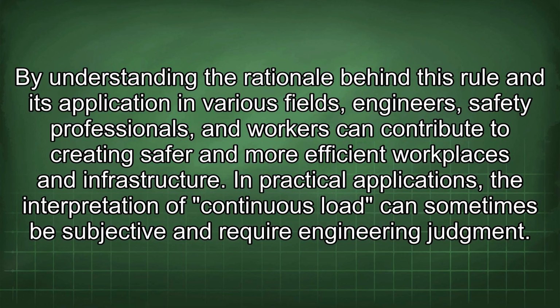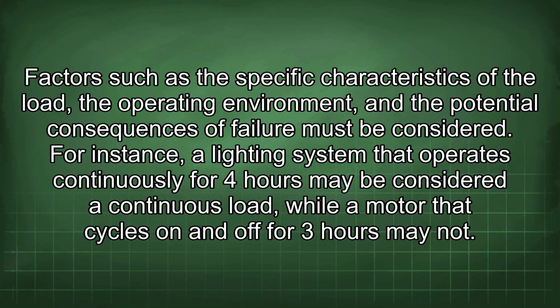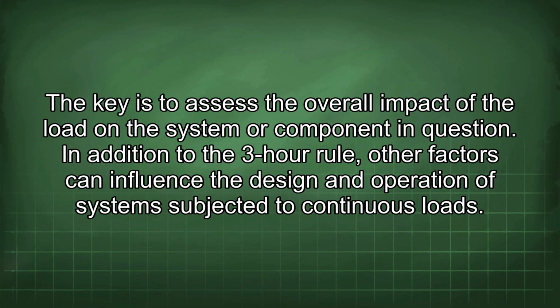In practical applications, the interpretation of continuous load can sometimes be subjective and require engineering judgment. Factors such as the specific characteristics of the load, the operating environment, and the potential consequences of failure must be considered. For instance, a lighting system that operates continuously for 4 hours may be considered a continuous load, while a motor that cycles on and off for 3 hours may not. The key is to assess the overall impact of the load on the system or component in question.